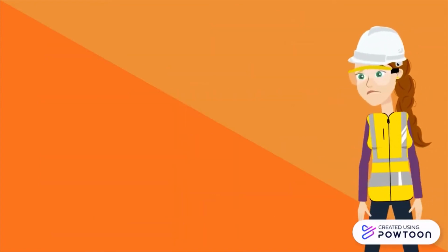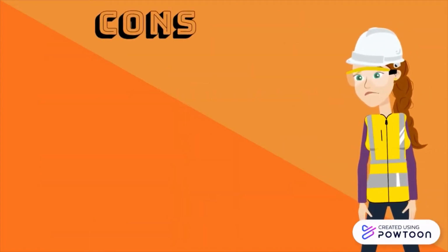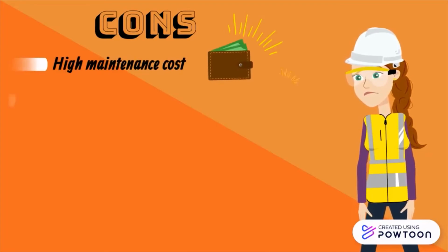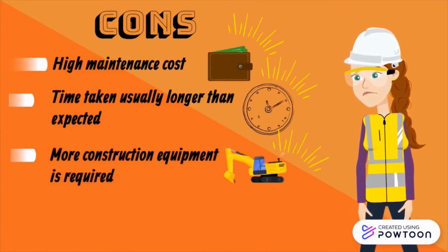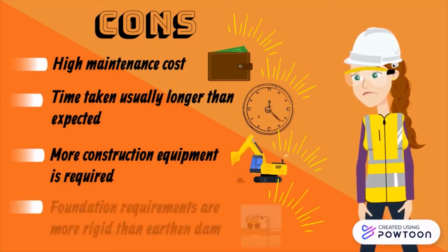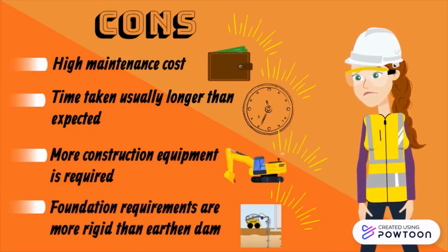And of course, there are the disadvantages. First, high maintenance costs. Second, the time taken is usually longer than expected. Third, more construction equipment is required. And fourth, foundation requirements are more rigid than for the earth-fill cofferdam.